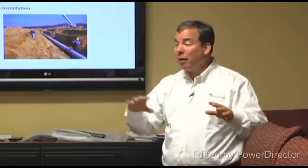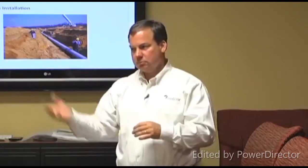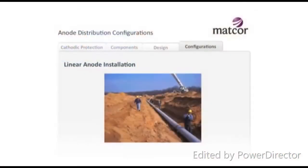We do have copper grounding systems, so we know that we're going to have to put a lot of current into the ground because the copper is going to suck up some of it. And we said, great, we can put the deep anode system in, but then you're going to have to test it. And if there's some areas, because again, I don't really control where current's going with the deep anode system, if there's some areas of that pipeline that aren't getting enough current, we may have to put some more systems in.